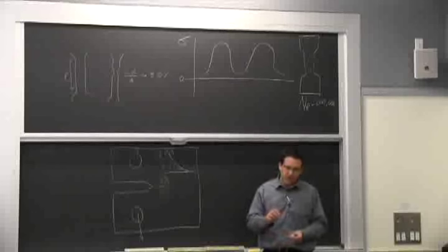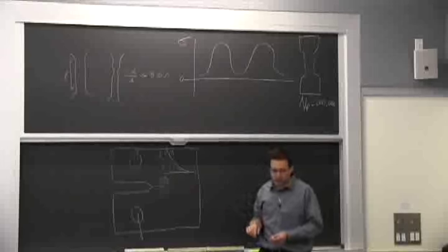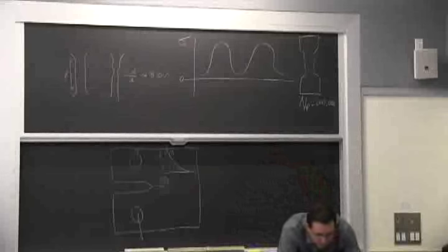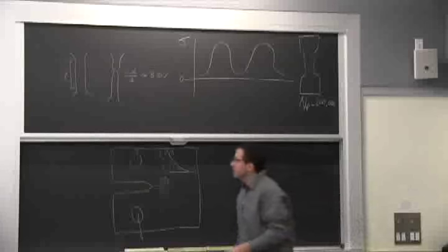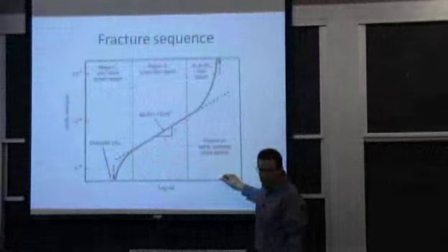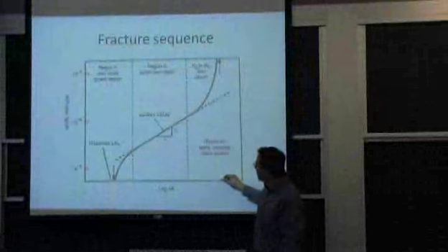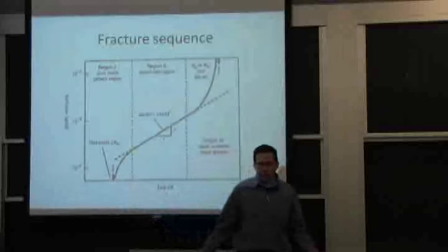So that's what I was going to say: for fatigue, normally K is small. If we go back to one of the plots we had, it's a log scale here. If the failure of the material is at, say, 50 megapascal square root meter, when it starts to crack here, it's of the order of 1 to 5.